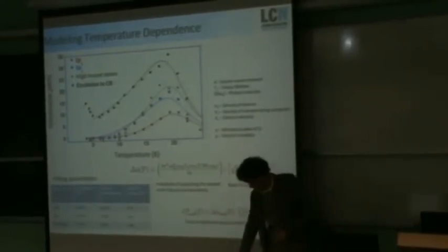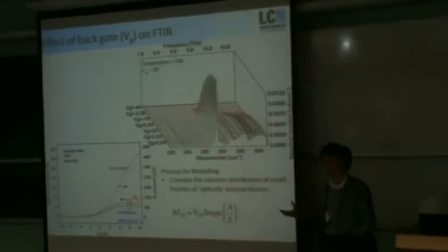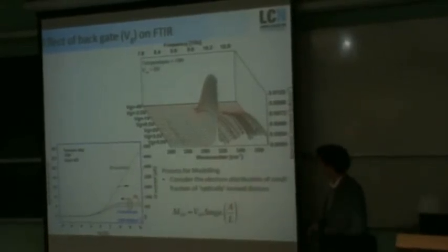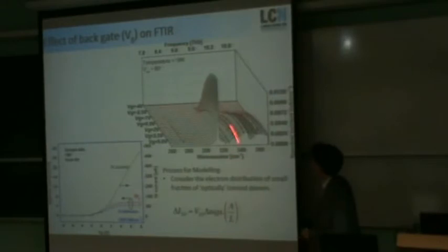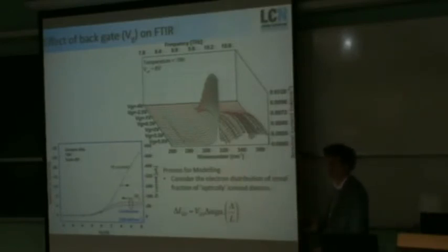So there's another important factor here: we have the back gate in this device. The optical response here changes significantly as a function of the backgate bias. Initially one might think that this would just follow the actual DC current through the device. But somewhat surprisingly, we've found that that's not the case. You get this saturation here, which doesn't follow the current. In this scenario, the current just keeps going straight up, but the optical response tails off, levels off in this region.